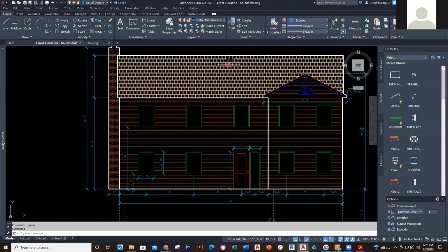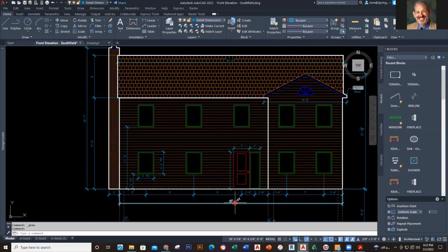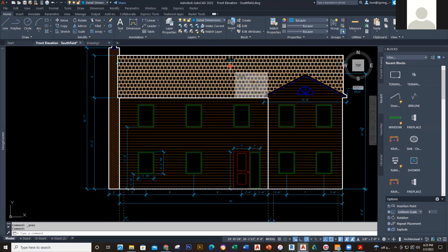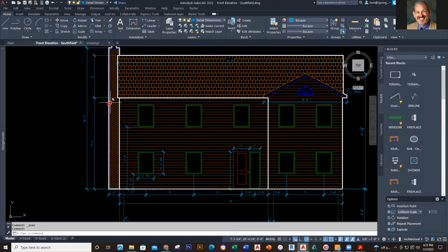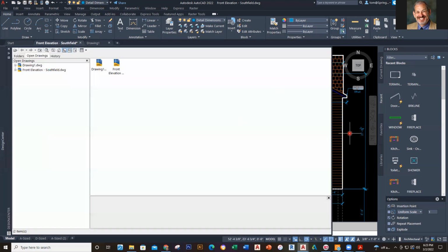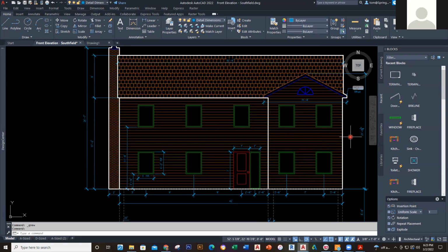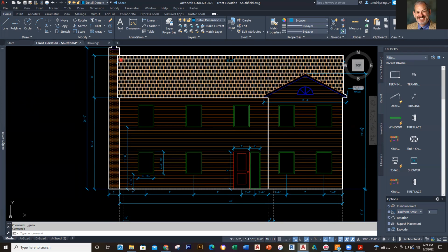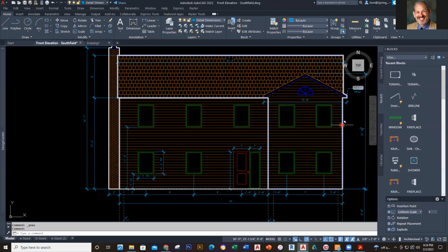All right. So you got 42 feet 6 and you got 42 feet. If I want half of the 42'6" to appear on each side, how much will go on each side? 3 inches. Yeah, 3 inches. So I'd go over 3 inches and then up 8 feet, then all the way over my 42'6" and then down. And I'm just going to draw the perimeter.